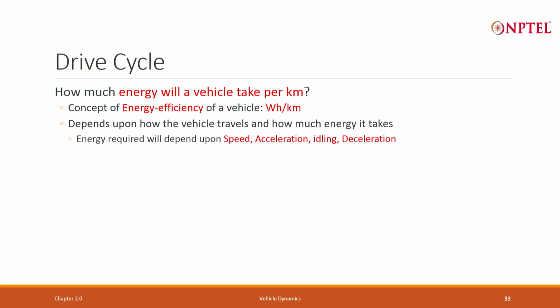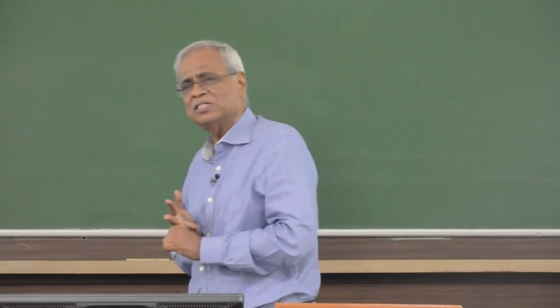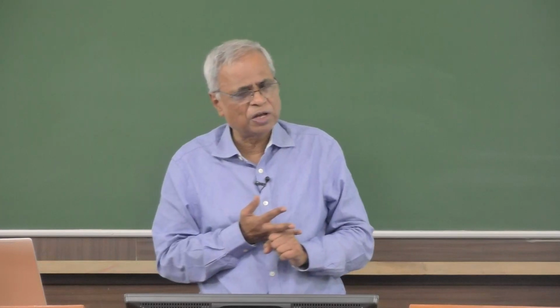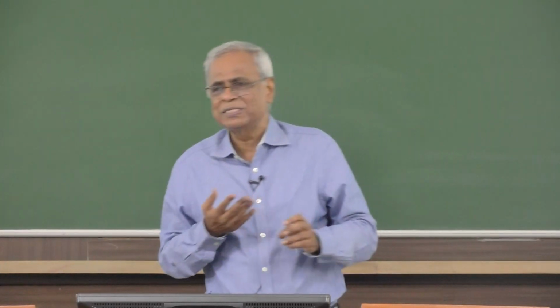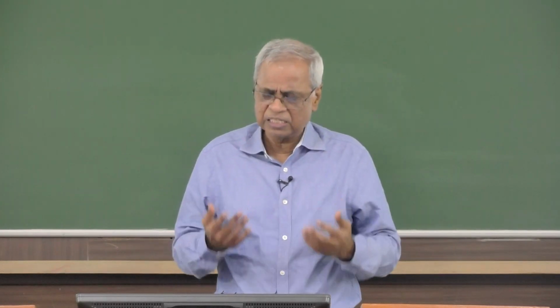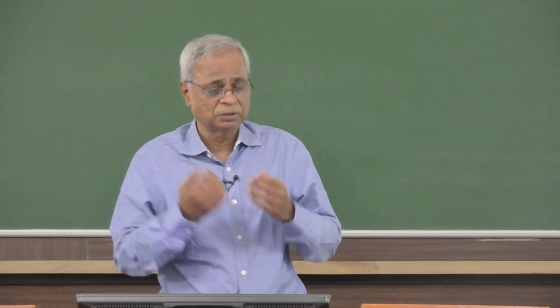When it decelerates, it gives you back some energy, but only a fraction of it. So, at what speed you travel, for how long, what is the acceleration, for how long, from what velocity to what, how much do you decelerate, for how long, how much are you idling, all these things become an important component in the amount of energy consumed.